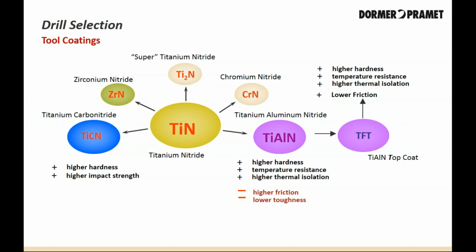We offer drills standard that are coated with TiN, TiAlN, TiAlN Top, and AlCrN Top. Anytime you see a coating offered as a dash top type coating, this only means that there is also a post-coating or smoothing process performed, which takes away any imperfections on the surface of the coating. This works almost like a polishing process, which can greatly improve the chip flow. Our surface treatments are steam oxide, bronze oxide, and purple bronze oxide. Although these surface treatments slightly increase the surface hardness, they are mostly applied to protect the drill from rust and corrosion.